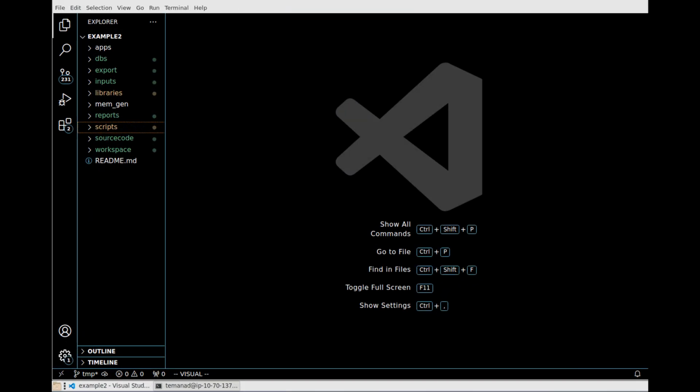So now that we've run timing back annotation and created our activity file, in this case we used a VCD file, but we could have created a TCF file or SAIF file or one of the other formats. What we're going to do is estimate the power consumption that we actually consumed during this simulation under this specific test bench, under this specific workload,